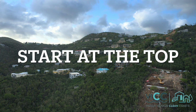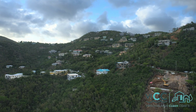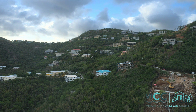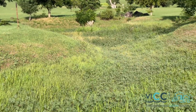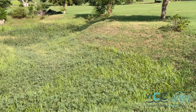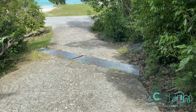Start at the top. Address surface water at the highest possible point on your property. Fix the problem before the location of the erosion. You will deal with lower volumes of water this way. Slow water down. As water moves downhill, it picks up force and speed, causing erosion. If possible, slow it down. This may mean directing it across a hillside instead of straight downhill.